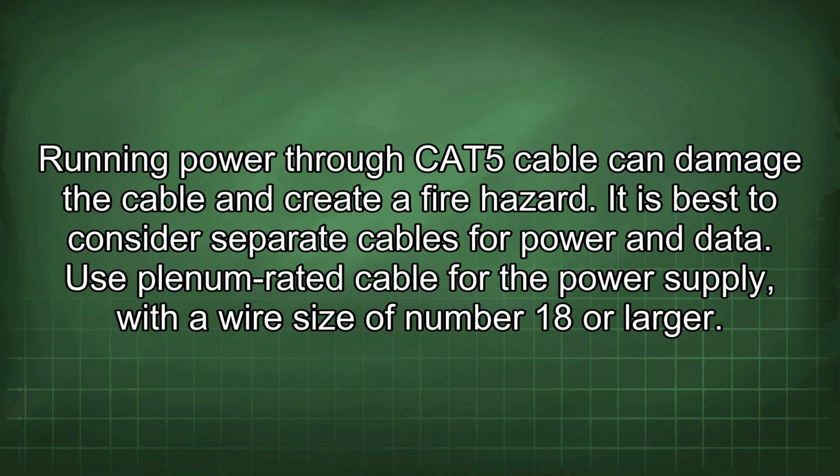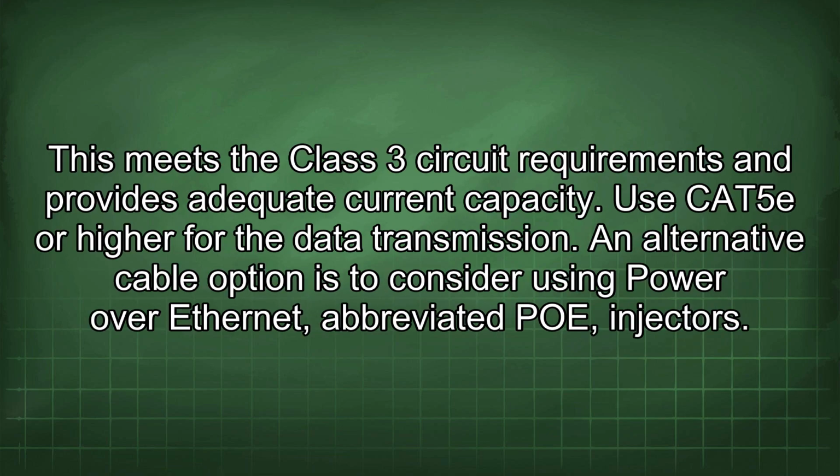It is best to consider separate cables for power and data. Use plenum-rated cable for the power supply, with a wire size of number 18 or larger. This meets the Class 3 circuit requirements and provides adequate current capacity. Use CAT5E or higher for the data transmission.